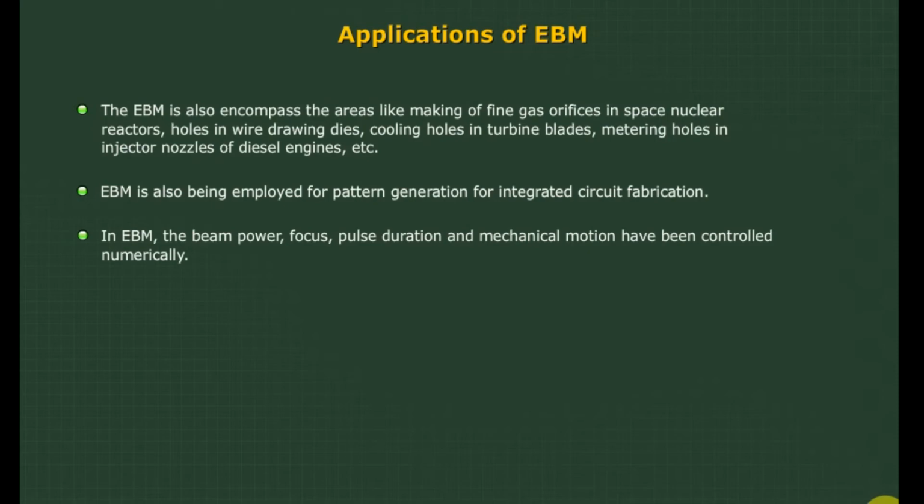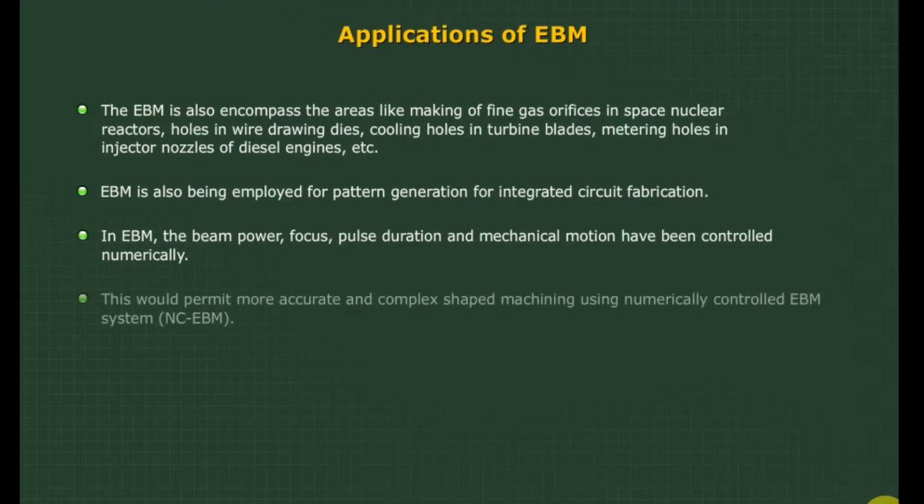In EBM, the beam power, focus, pulse duration, and mechanical motion have been controlled numerically. This would permit more accurate and complex-shaped machining using numerically controlled EBM system, NC-EBM.